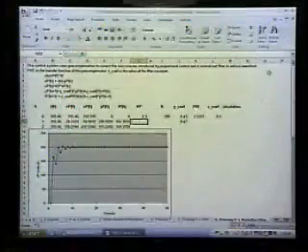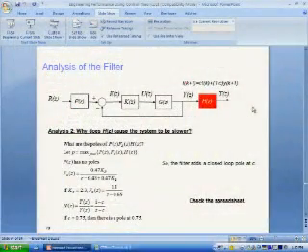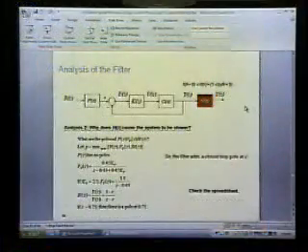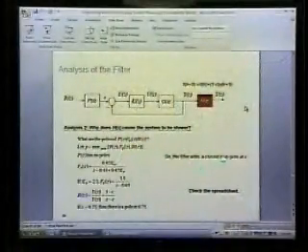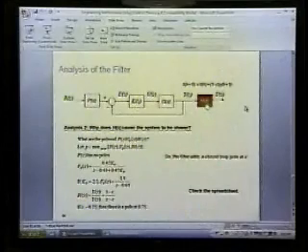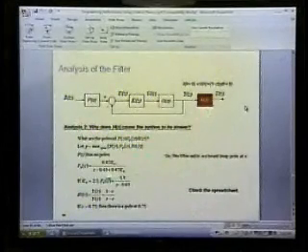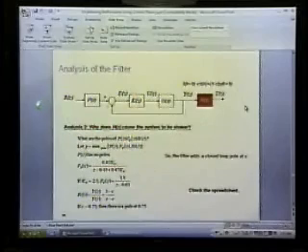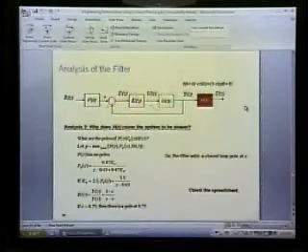You've actually already answered the next part of the question, which is why is it slower? Why do we change the dynamics of the system? And that's this analysis over here, which is essentially what you just said. But let me make sure we're all clear here. So why was the system slower? The answer is that when we added this over here, the poles of the system are the product of this times this entire system right here times this system here. So this entire feedback loop. So that's this part over here, those three sets of poles.